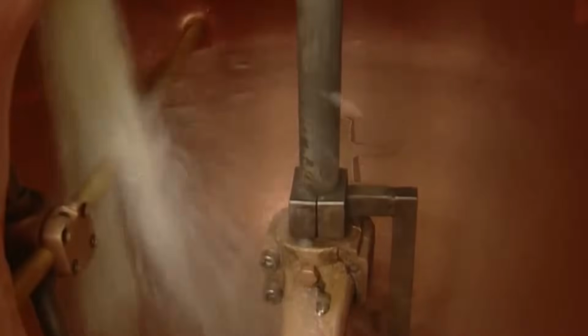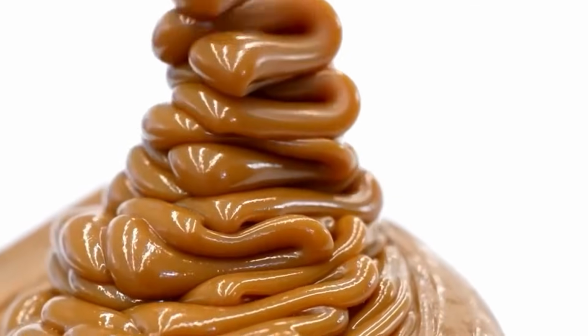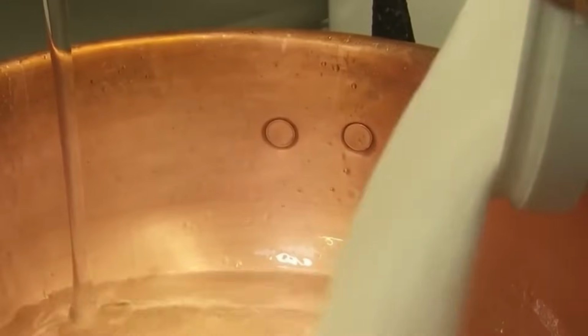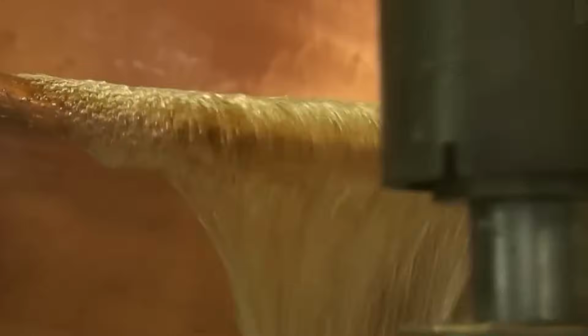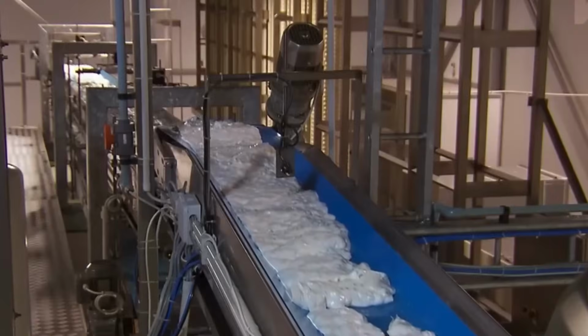The granulated peanuts are then pneumatically transferred to storage silos for batch-based dispensing into the peanut butter blend. The peanut butter layer is produced in a batch mixing system where peanut granules are combined with vegetable oil, sugar, salt, and stabilizers in a ribbon blender with temperature regulation. The mixture is homogenized using a high shear inline mixer and heated to 48 to 52 degrees C to achieve pumpable viscosity.